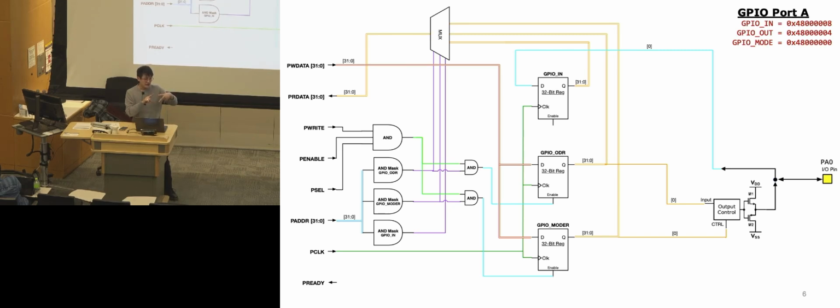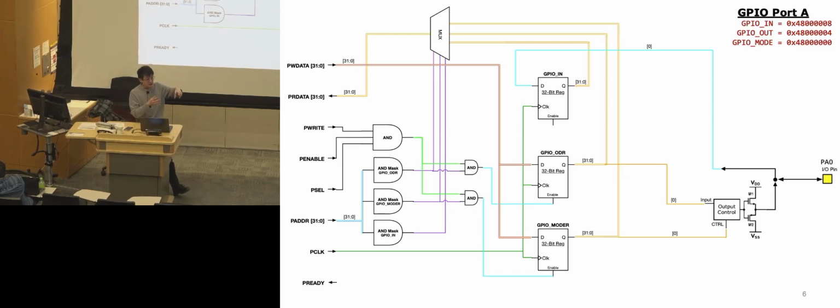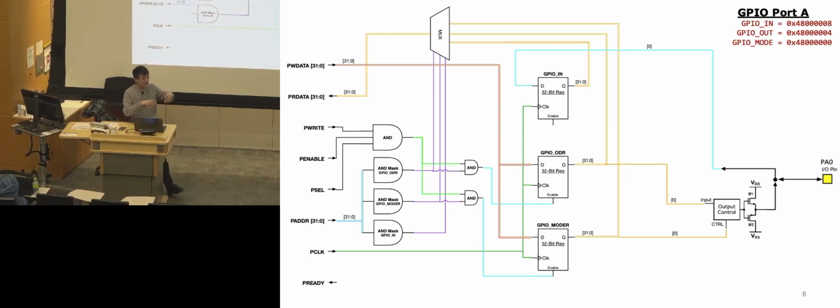One writes or stores values to the mode register, which sets this GPIO to, say, output mode analog pin. And then the next instruction, or somewhere down the line, is another write instruction to the output register, which outputs the actual value through the GPIO pin, the physical pin.